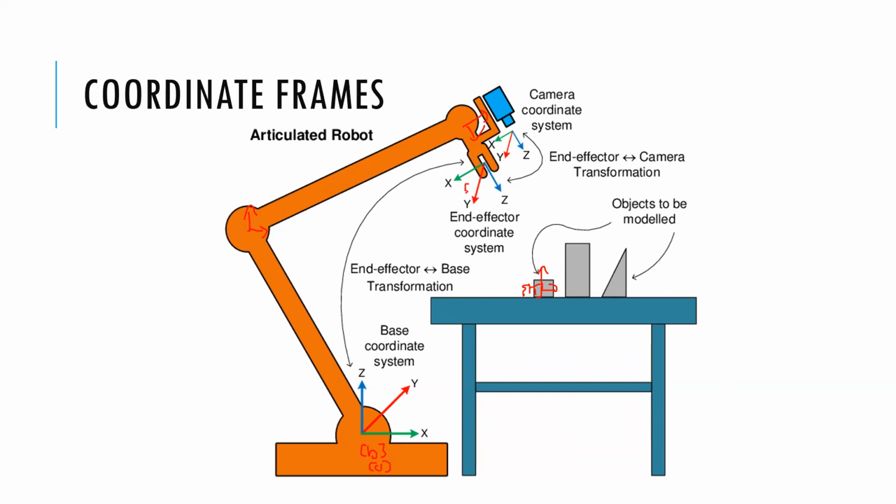And this is my end effector here, and this is my camera system here. I detect this object, and I want to go grab that object. How do I know where this object is with respect to the base of the system? So go through that here. So we know where the end effector is, and we also talked later on about the kinematics. So these are joint variables, Q1, Q2, Q3, and so on for an n-degree-of-freedom system. And I can compute the end effector location with respect to the base.